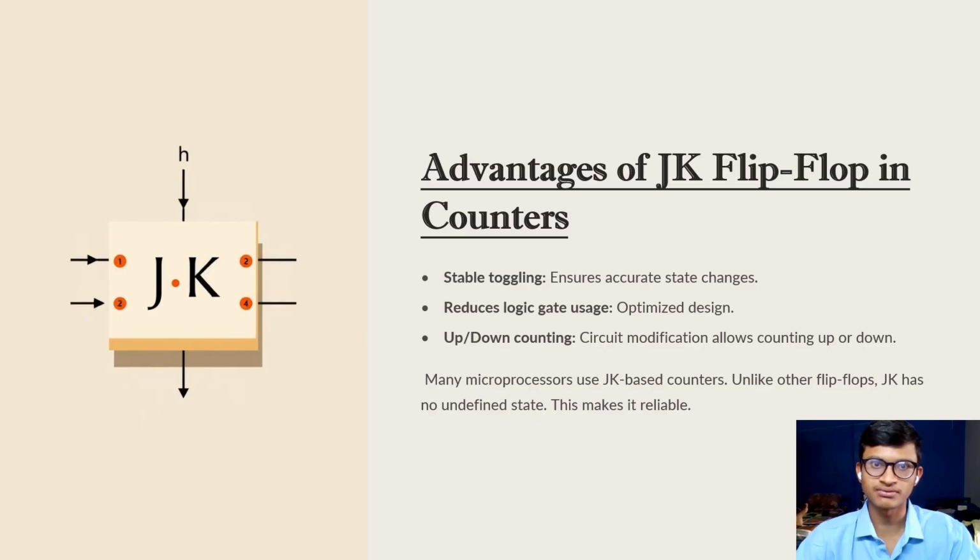We can use them for both up counting and down counting, which makes them flexible. And unlike SR flip-flops, they don't have any undefined states, so they are more stable and reliable. That's why JK flip-flops are the best choice when designing binary counters.